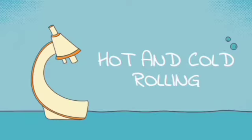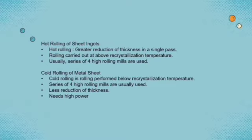Next is hot and cold rolling. Hot rolling of sheet ingot allows greater reduction of thickness in a single pass. It is carried out above the recrystallization temperature. Usually a series of 4-high rolling mills are used. Cold rolling of metal sheet is rolling performed below the recrystallization temperature. A series of 4-high rolling mills are usually used. Less reduction of thickness is achieved and it needs high power.